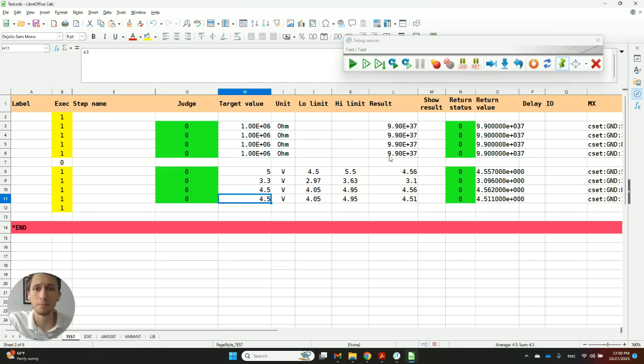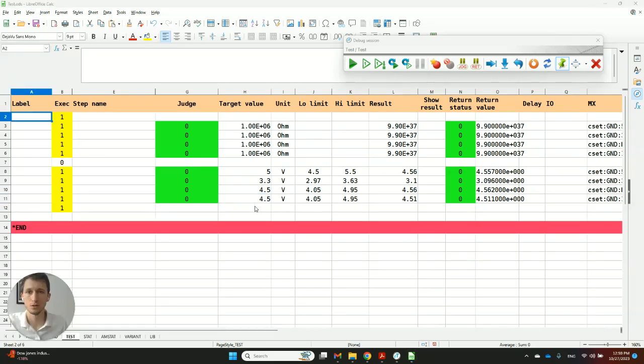And now we have a test sequence that confirms that none of the pins are shorted, so it's good to power it up, and then verifies that the device powered up correctly. This example shows you how easy it is to perform a measurement sequence utilizing test equipment, in this case, a multimeter and a switching system.